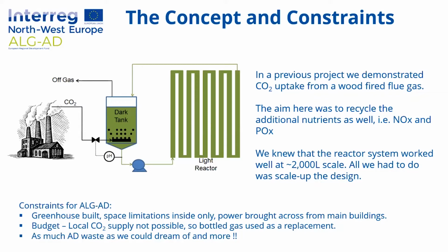So essentially, we control the reactor based on pH, but not shown on the screen, obviously, we control the reactor in terms of dissolved oxygen content and also temperature as well, and nutrient content and things like this. Obviously, there's an off gas that comes out of this system then, and those are basically the off gases of any unused CO2 that's in the system, but also obviously the algae photosynthesize, so you get oxygen coming out of there as well.